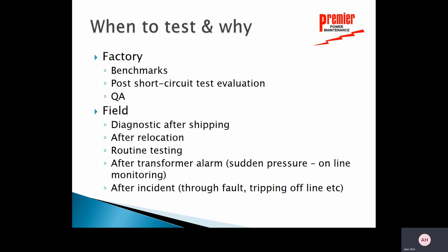So when we look at it, it's when to test and why do we actually want to test? Well, at the factory, okay? At the factory, we want benchmark tests. That's very important. Now, understand that we've got benchmark tests, but there's some things different in the factory that might look different in the field. For instance, they may have a set of bushings at the factory floor that they put in all the transformers they make of that size. And when you get to the field, you install some different bushings, so there may be some differences there.